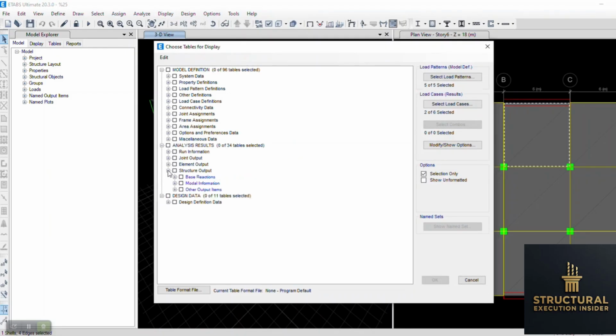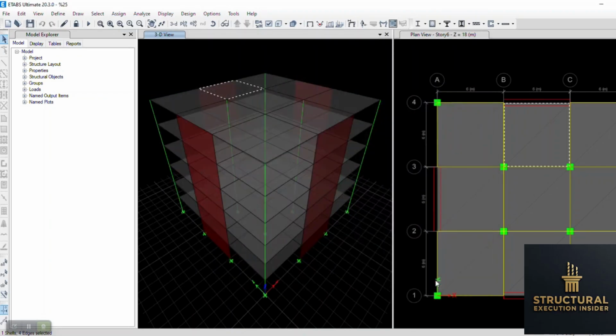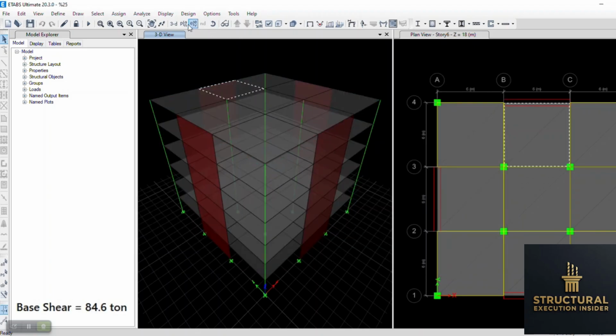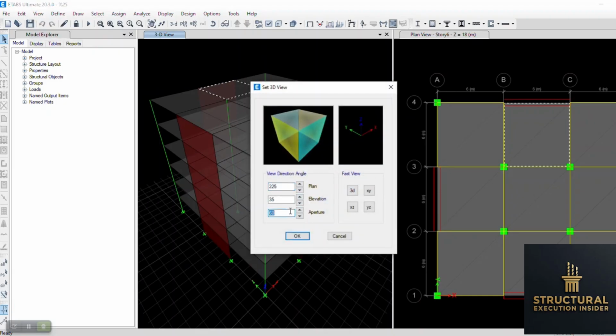But if we display deformed shape under EX, we immediately notice something different. The walls are now absent from lateral participation. The columns and moment frames are carrying the seismic response. The diaphragm still connects the system, so lateral force transfer remains stable and realistic.